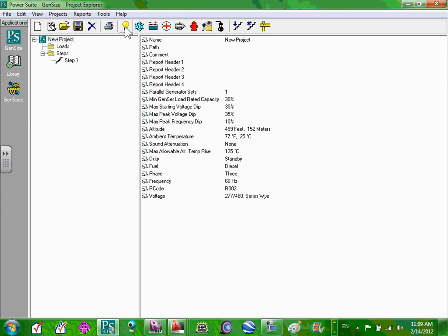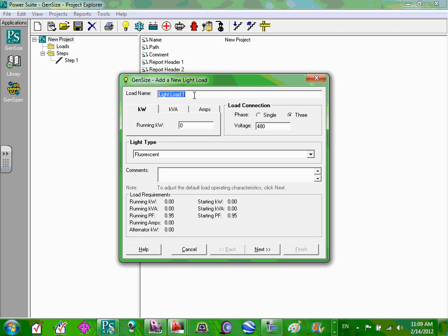So let's go here. Lighting. Can you guys see where this bulb is? Click on that baby. All right. Open it. So when you are here, I want you guys to type lighting panel LP. Cool. Type LP. Go all the way to kVA. You can put the load in kW, kVA, or amps. I like kVA, so click on kVA. What did we say the kVA of that system? 69?